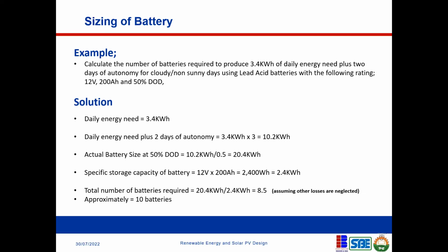Exactly. No, I think you are wrong. Because you can't do that. The batteries are rated 12 volts. When you connect 12 volts in parallel with 24 volts, the equivalent voltage is not going to be 24.